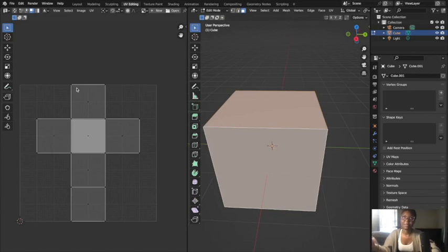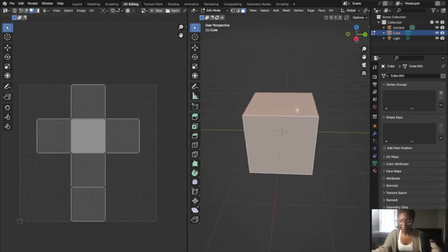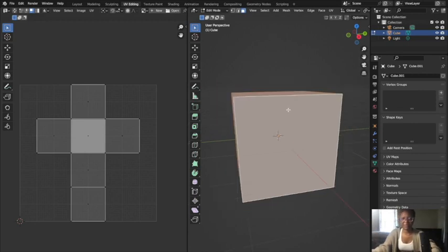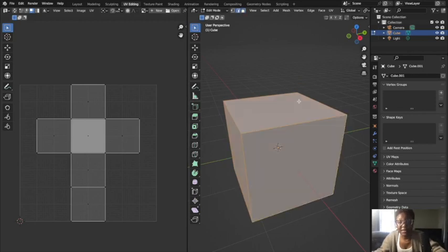And in some cases we might want to optimize this UV for texturing space, or if we have multiple meshes in one, we might need a little bit more space in this box, right? So it's important that we understand how to separate faces on a mesh to get a separate UV, because right now all these UVs are combined together, and we really want to separate the UVs.